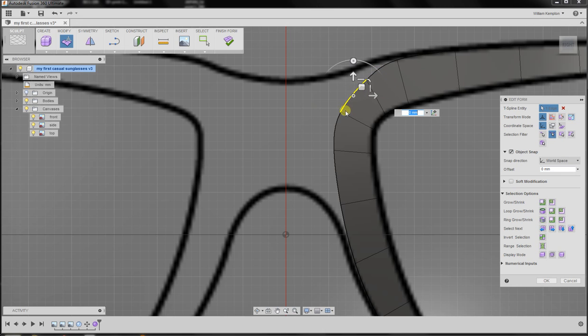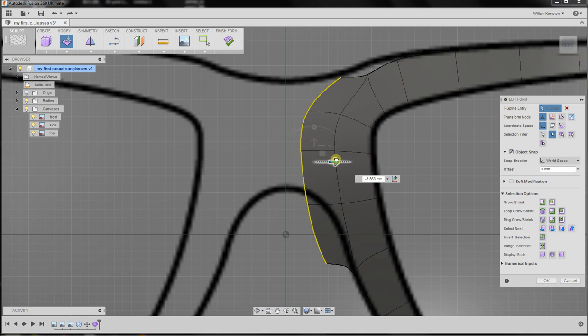I think what I want to do is I want to make 1, 2, 3, 4 edges. So I'll select these 4 edges, and I'll just drag out from holding down the Alt button, which somehow gave me a mysterious outcome, so I'll do that again. Holding down the Alt button, I can try even dragging the arrow, and I'll just scale them down slightly, because what I want to make another 4 faces, and I want them to be aligned to that red line you can see here, and I want them to be totally straight.